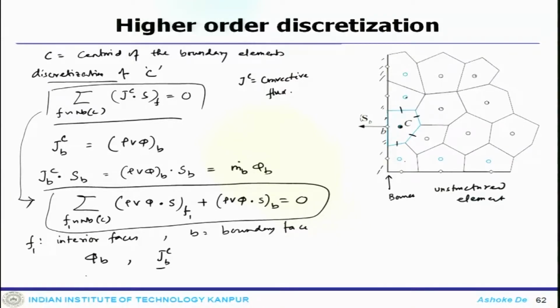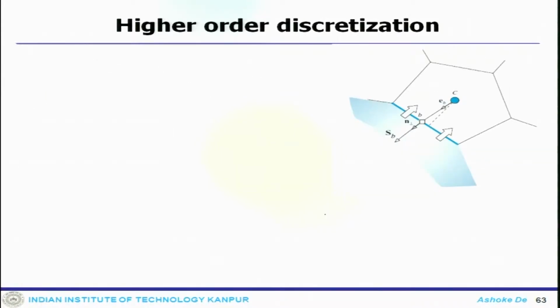If the boundary value is known, that is what we call a Dirichlet kind of boundary condition, and we have already seen how to implement that. If the surface flux is provided, then that is known as Neumann conditions or the gradient conditions. Now, that is the formulation at any boundary. Now, we will look at the inlet boundary conditions.